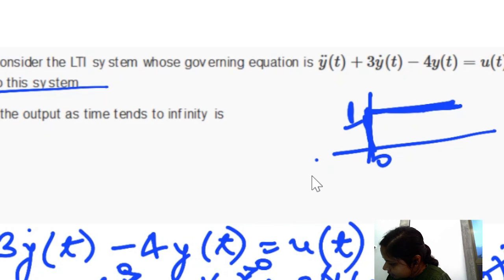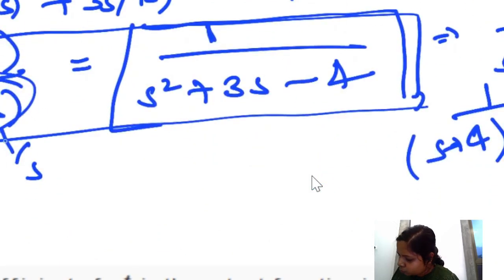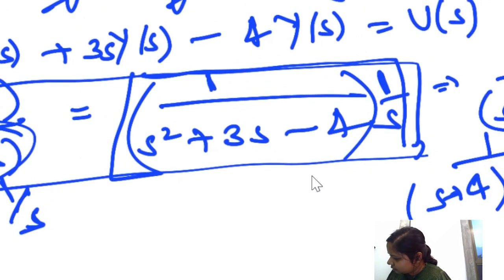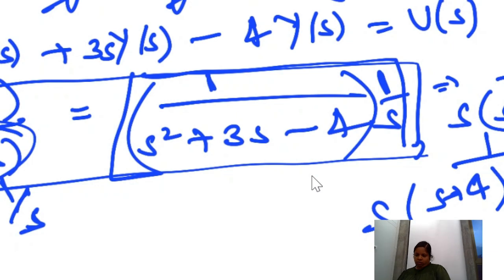When you take the Laplace transform of this unit step using the formula from 0 to infinity, what you get is 1 upon s. So this 1 upon s had to be used here. You multiply this by 1 upon s. So here there would be an s, here also an s, and here also an s, and there would be another term C upon s. I had missed this s because this is a unit step response, you have to know the input to the system to find out the output. Now you tell me the coefficients.